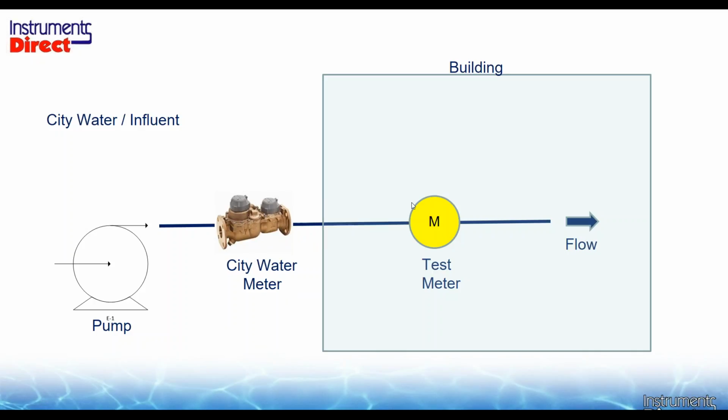In this case, a large pipe size with a wide variety of high flow and low flow, you would use a compound flow meter, which is basically a 10-inch meter with a sidecar meter, half-inch to 1-inch diameter, that measures low flow. It all comes down to velocity.